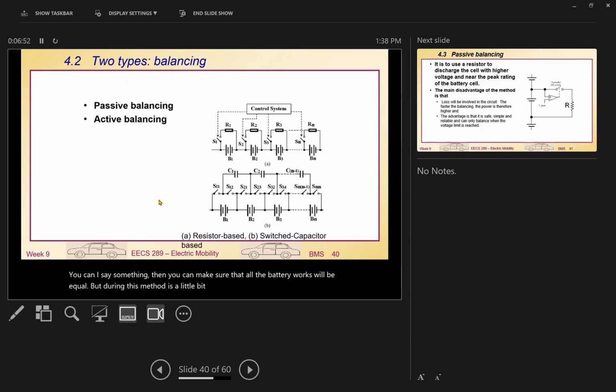If you want to balance the voltage from this battery back to this battery cell, because it's quite far away, we need this one to connect to here and this one to connect here and so on. It's some kind of ladder delay anyway. But as I said, the switching frequency here will be really quick, say 20 kilohertz, maybe 100 kilohertz, so it only takes 50 milliseconds or so to transfer the charge. So even though they are slow, they are still really fast anyway. Within seconds, all the battery cells can be balanced.